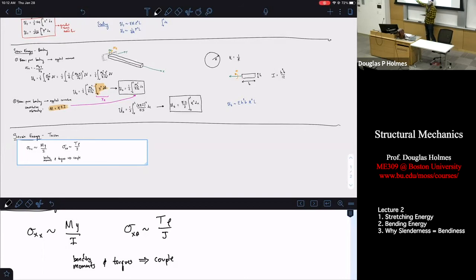So that in bending is usually measured as y, where y is sitting right at the neutral axis of your beam, and the bending stress will go linearly away from there. In torsion, one of the things you might remember is if you twist an object, there's no stress along the neutral axis of that beam. That would start at 0 here. If I put in 0 here, this is 0. Bending is the same thing too. You bend an object, the neutral axis, hence its name, neutral, is going to have no stress. When I put in y equal to 0 here, the neutral axis has no stress. And both of these quantities are modified by how rigid the geometry is. You can remember all the stuff we did in mechanics of materials where you look at hollow rods that you twist versus complete cylinders that you twist and so on and so forth.